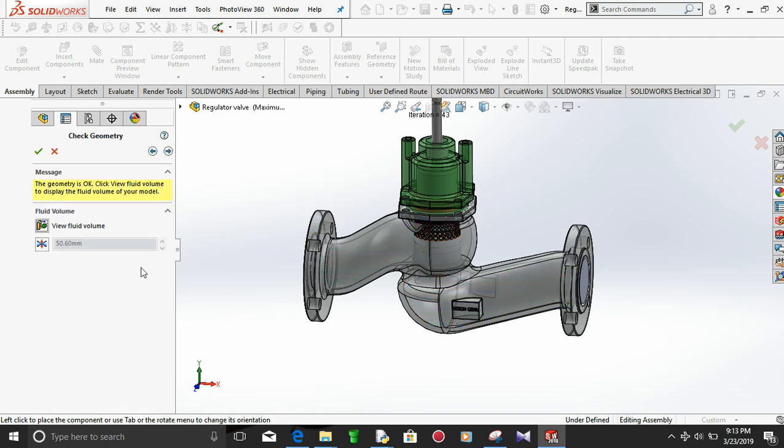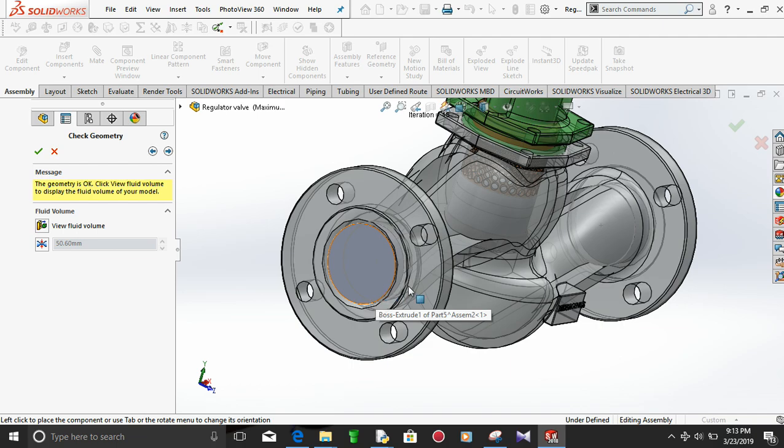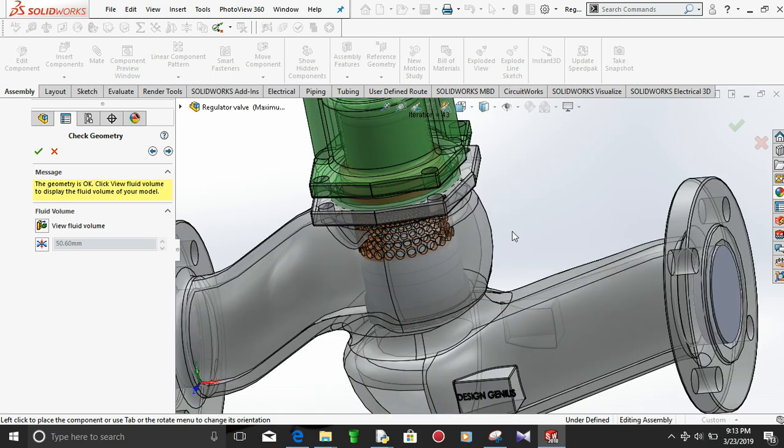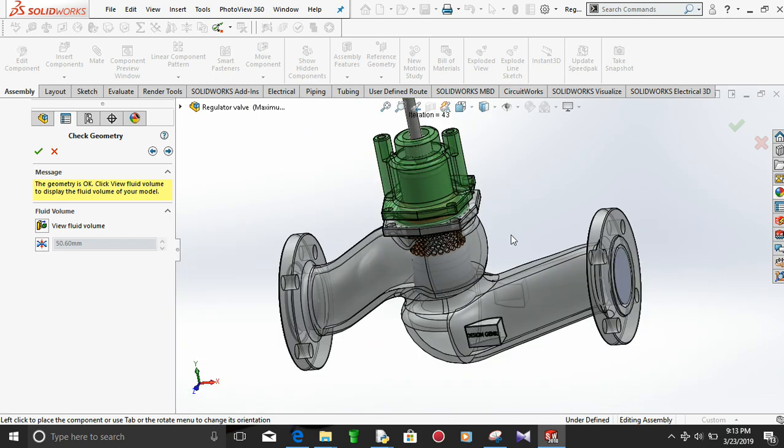Let's start. To start, we need to make sure that the geometry is closed, meaning that our structure here is closed. Now here it is closed, here it is closed. Now to work with SolidWorks Flow Simulation, you need to make sure that you have activated SolidWorks Flow Simulation.